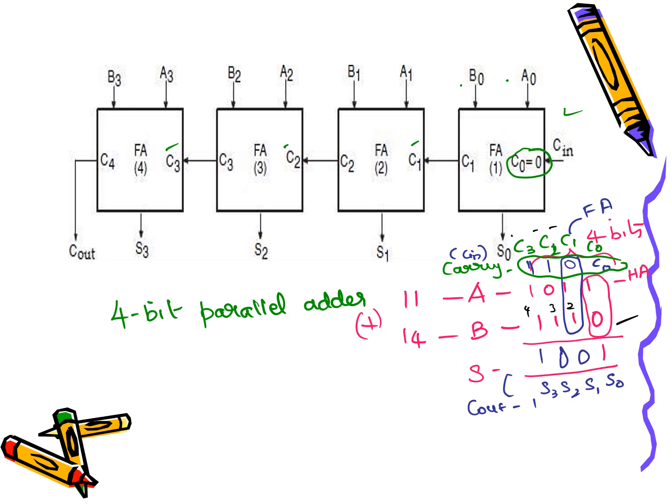So I'm moving to the 4-bit parallel subtractor. If you want to perform subtraction, actually you'll be thinking you have to take four full subtractors. That is also good, but as of now we perform even subtraction using an adder circuit. So if you want the same adder circuit to perform a subtraction, it is always recommended to take the complement of the subtrahend.